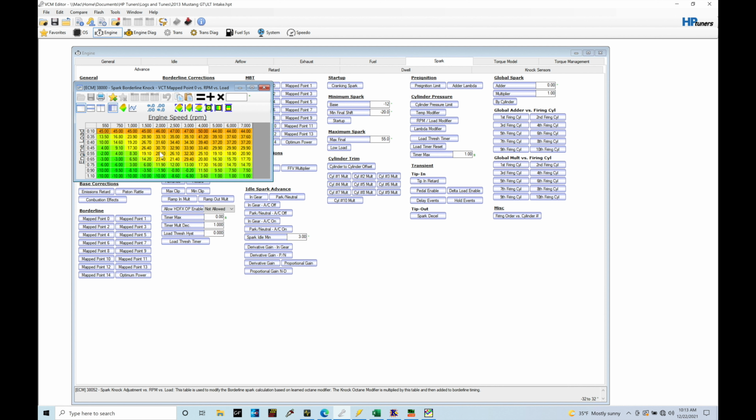So these values, again, look arbitrary, but they are very specific, and they're done in a specific manner to avoid knock or pre-ignition and make good engine power and torque. But how do these values actually get us to the point where we're firing off the spark plug? Let's break this down. Let's jump a step backwards and talk about the Otto cycle, because you may not be familiar with the Otto cycle. I want to break this down so it's very clear how the Otto cycle works in terms of talking about the degrees of rotation of the engine and then how that fits into what we're talking about in our values here in the table.